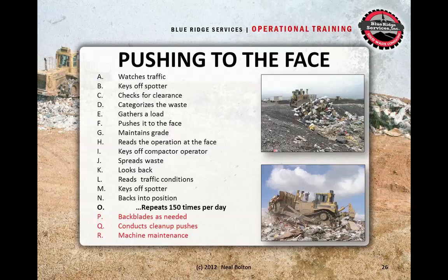And what we find is there are lots of things that happen out there. Some of it's traditional, where a dozer operator may, in between loads, when there's nothing to do, go find something to do. Go backblade an area or push waste someplace where it doesn't need to be pushed, or do some cleanup pushes that are not productive. And keep busy because, hey, that's his job or her job to operate the dozer. And so they're going to do that all day long because that's what they're assigned to do, instead of focusing on making only production pushes and only doing work when there's work to be done.